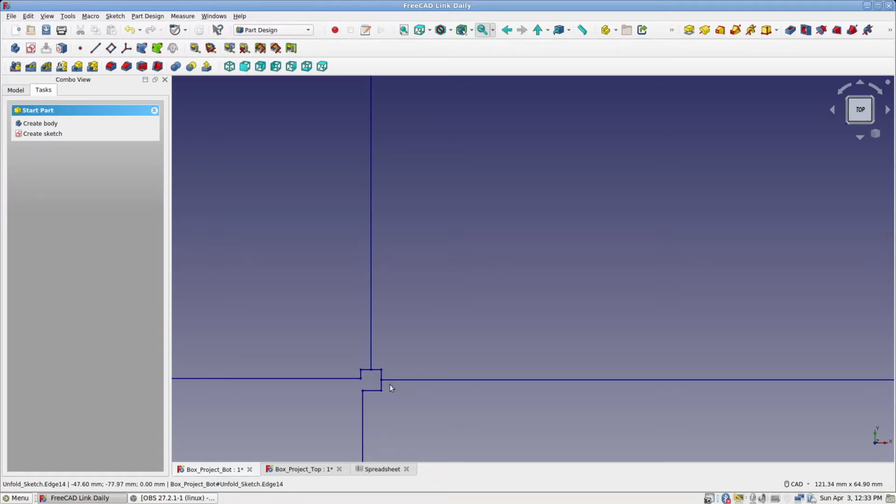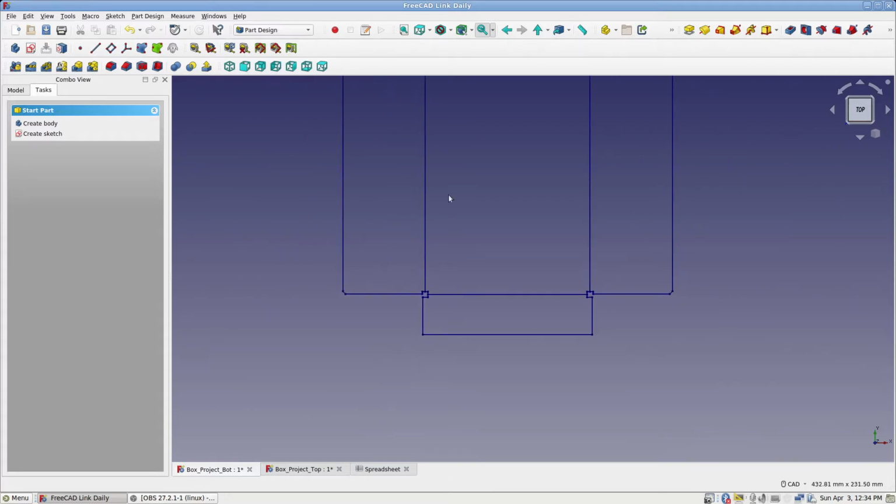I did it with a hacksaw blade, which is really simple, and the video that I put out there that actually shows this box being made will show how that's done. So you've got to take this with a grain of salt. I suppose if you were laser cutting these parts out, this would not be a problem, but if you don't have access to a laser cutter, this is going to be a problem. So we'll just leave that as modeled, but be aware of that feature there.